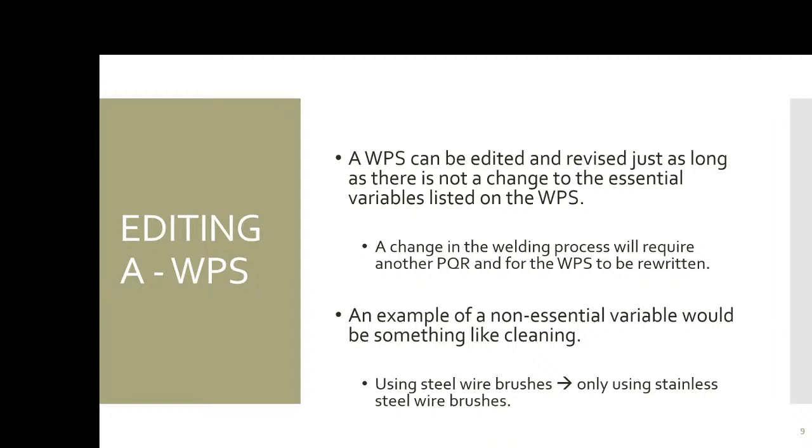So when we're going into WPSs, just remember that a WPS can be edited and revised just as long as there aren't any changes to essential variables. But a PQR can't. An example of a non-essential variable that you could change on a WPS would be something like cleaning. On my next revision, I only want stainless steel wire brushes to be used.